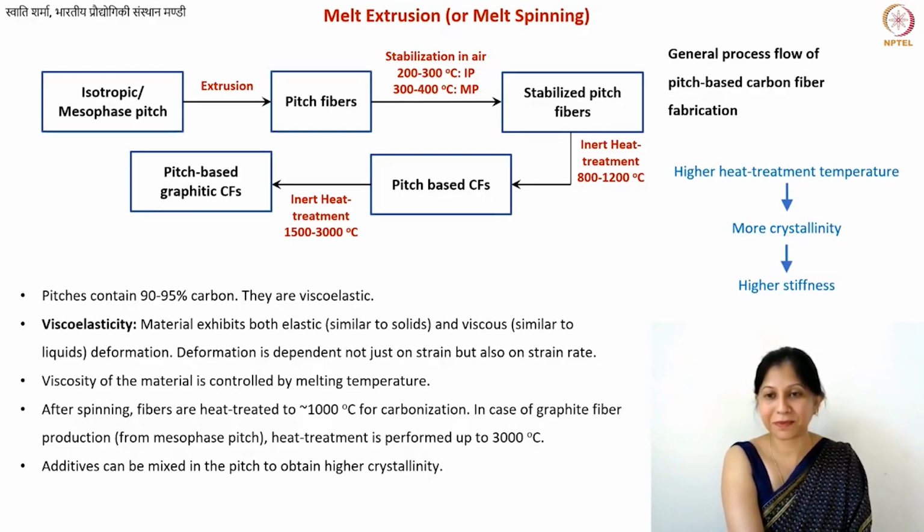Okay, for all carbon materials, this is our golden rule. The higher the heat treatment temperature, the higher the crystallinity, the higher the stiffness. And when we say stiffness, we are talking about the Young's modulus.